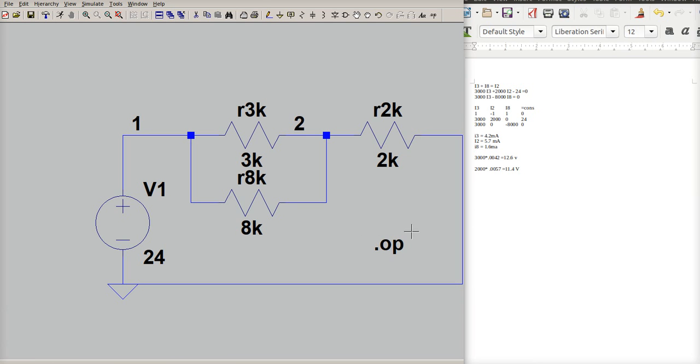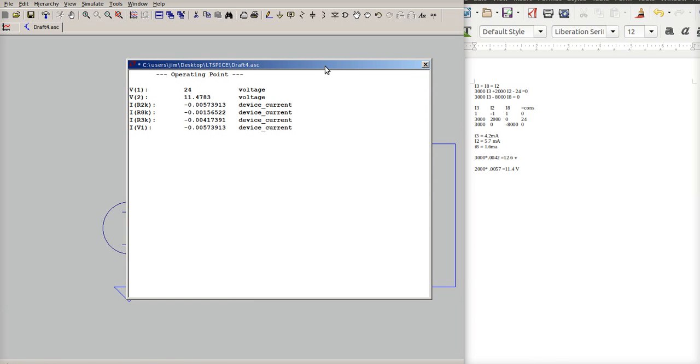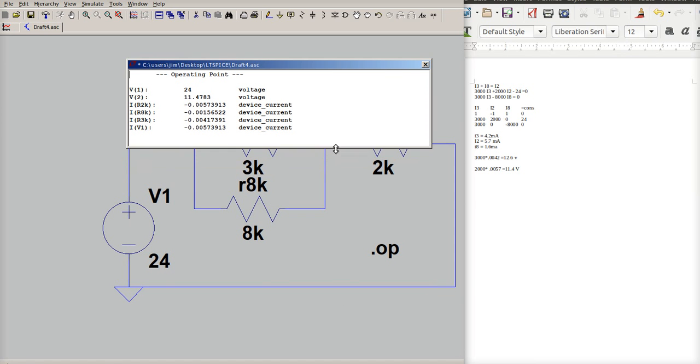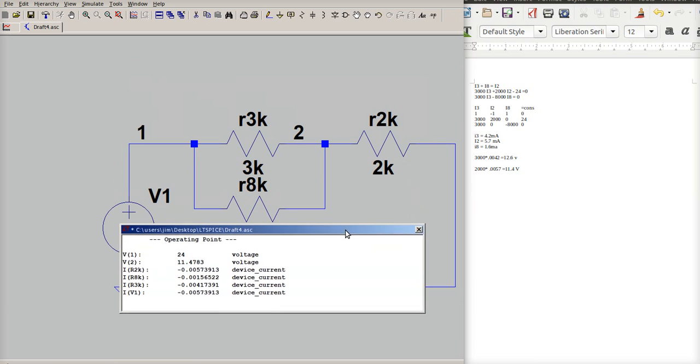So this is telling me I want to do DC analysis on this circuit. You can do DC analysis, you can do AC analysis, you can do transient analysis, frequency response, all sorts of stuff. Okay, that's for later on as you get into the field. All that stuff opens up for you. So now I'm just doing DC analysis, and there's this little running person here, or I can do simulate run. Like any Windows program, it's multiple places. Alrighty, so now I get some results. I'm going to make that box very small, and I'm going to go way down here with it.